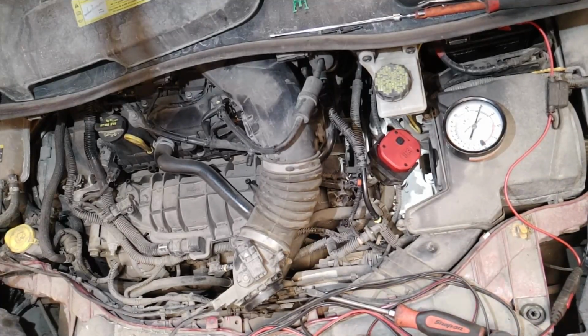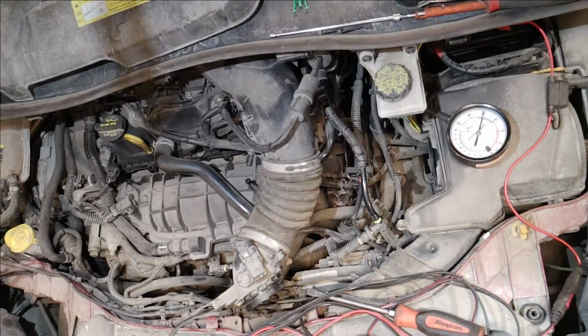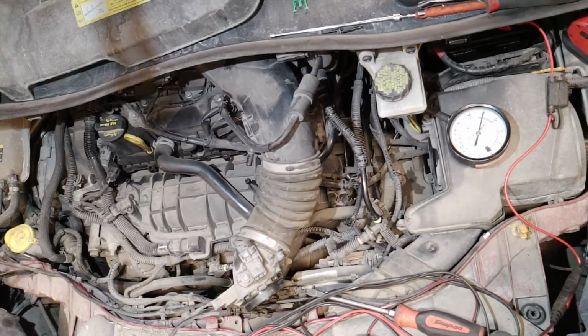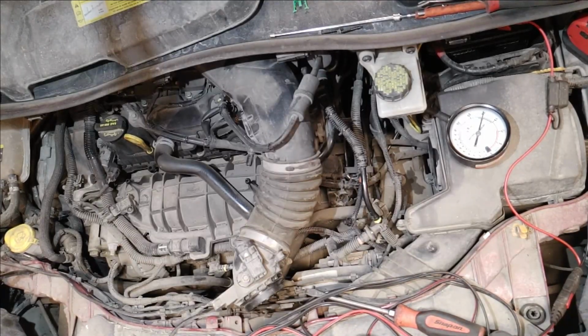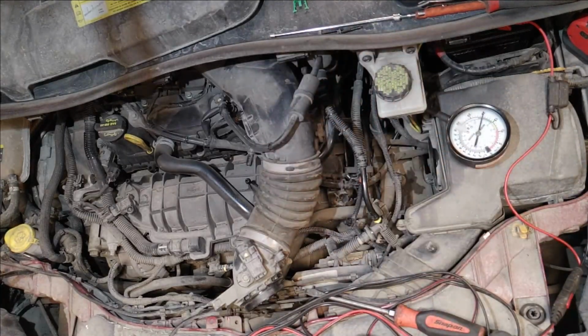That's for the P1450. So it's for sure that I'm probably going to have some lean codes in the system now, because I have a bunch of hoses that were taken off, but I'm okay with that. So the purge valve is no good. There's a cooling issue on the car, and these are bulletins straight from Ford, so I'm not really in the place to discredit what Ford is saying. So this one was true. The purge valve is actually broken. I was able to verify this one.